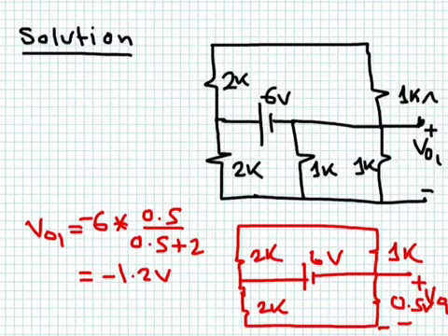It's very simple to see in this circuit. Once you have built this circuit, you have to analyze it. You have 1K in parallel with 1K, so this is going to give you half a K. So the circuit now looks more simplified this way. This looks like a voltage divider. You have 6 volts and you have 2 resistances. But remember the polarity of the drop, positive, negative, positive, negative. Then the output voltage you're going to get here will be negative.